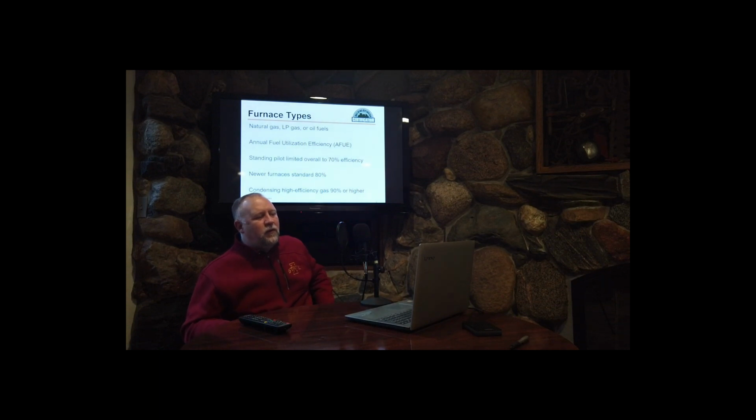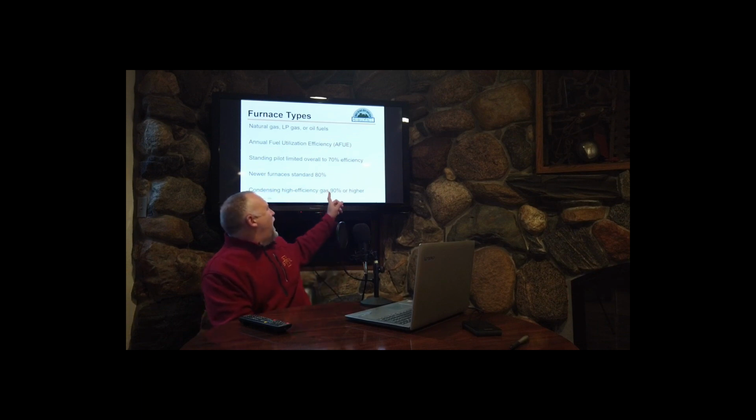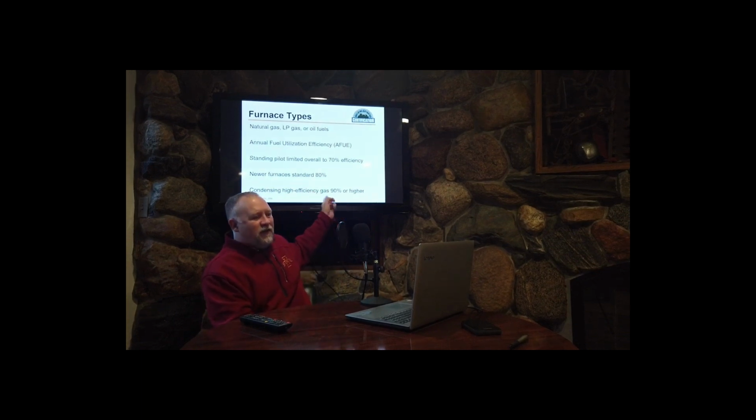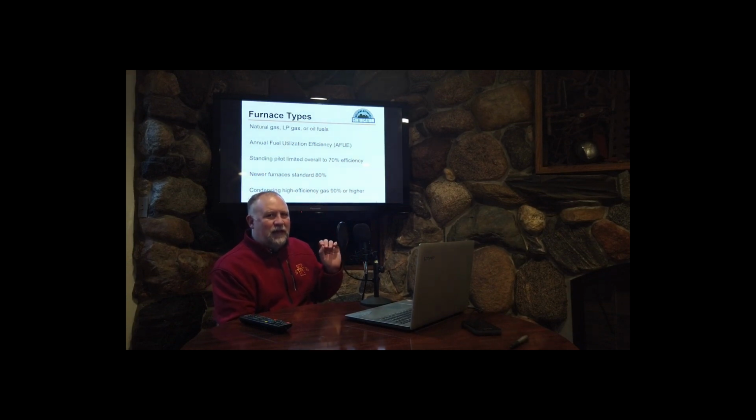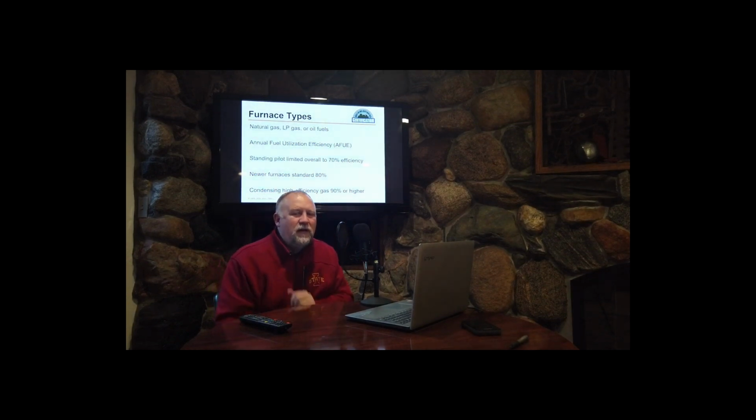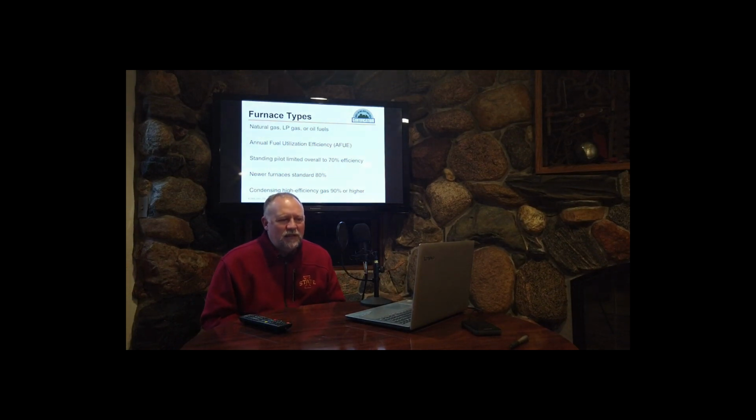We can get up to the upper 80s, even the low 90s in terms of efficiency. You might buy a new Lennox Pulse furnace that is 94% efficient. Something important to understand, once we reach 88% efficiency, it's not on the slide, but write that down: 88% efficient and above will cause condensing in the furnace. Now, condensing. Let's unpack this term for a second.